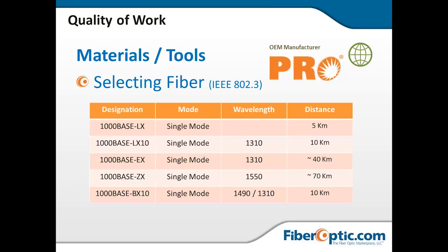At the BX10, really this is very similar to the fiber to the home type of deployments, where you have maybe a 1550 going back, or I'm sorry, using 1550 for the RF signal down, but then you would have the 1490 and 1310 for your Ethernet and internet connections. So that is typically spec'd out at about 10 kilometers.